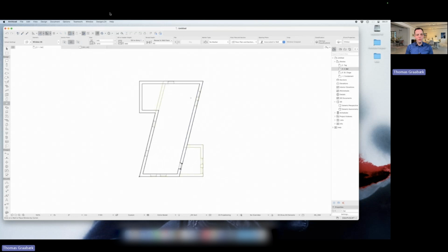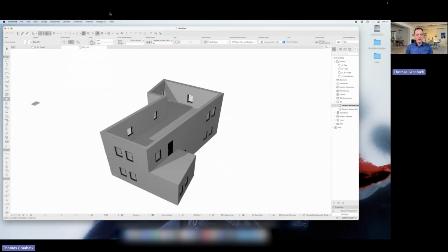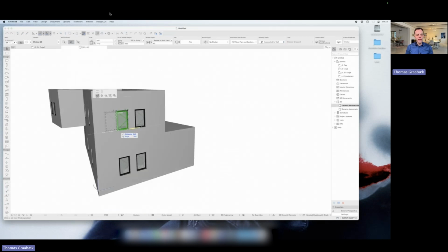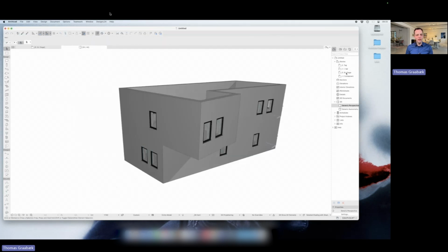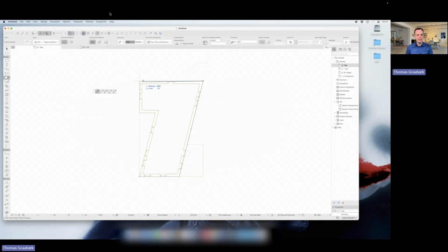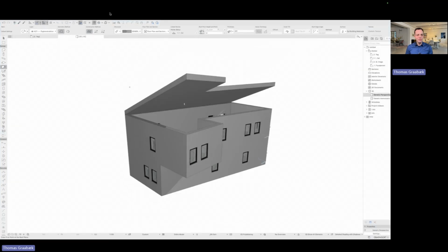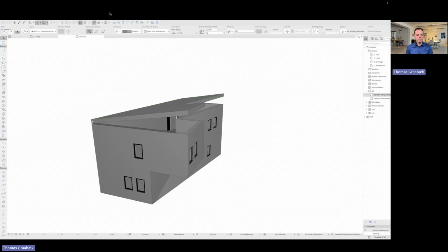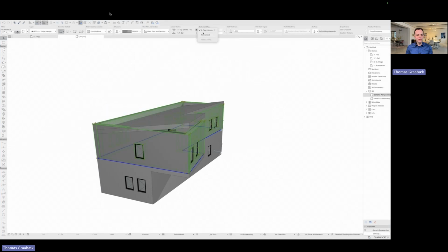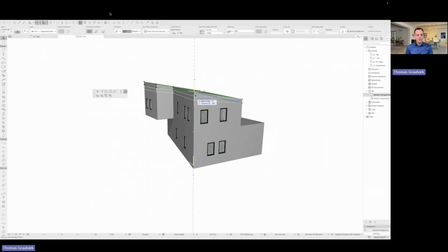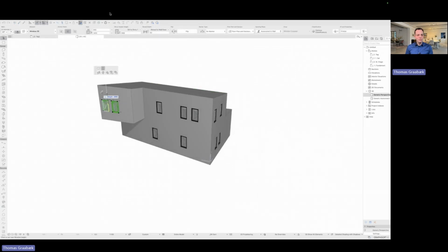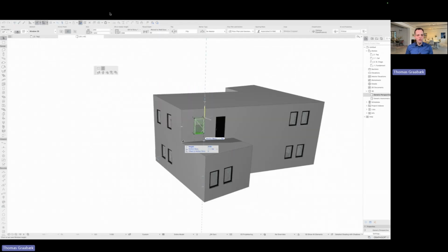We have included that property set that you need on your elements to be able to calculate the LCA. And we actually also made a bunch of building materials with CO2 values and lifespan already included. That means when you use this template, you can start modeling. And the second you put real materials on the model, it will start calculating LCA. If you don't have a template like ours, you might be able to get one from the local distributor of Archicad.